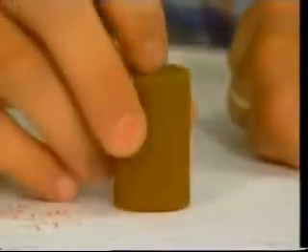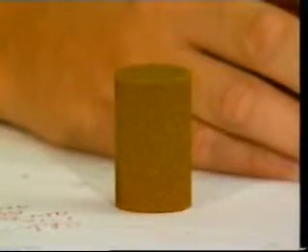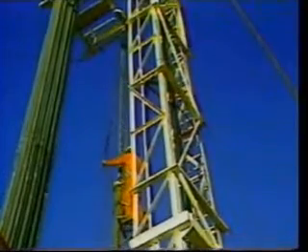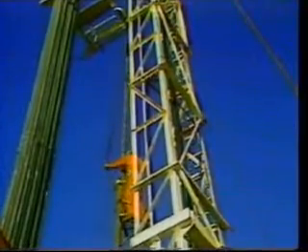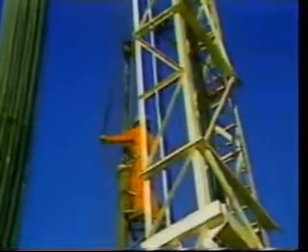Once a decision has been made to employ sand control methods, the wide range of techniques must be evaluated, from maintaining production at a rate that will limit sand production to a more sophisticated consolidation process whereby the sand grains are cemented or bonded together within the formation. However, before sand control techniques are employed, it is critical to use completion techniques that will minimize the tendency for sand to be produced in the first place.